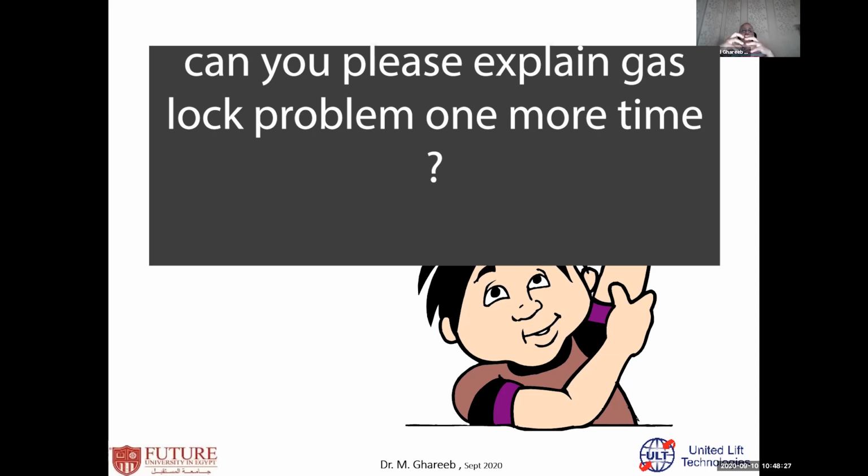If the volume of the cylinder is big, and the volume of gas is small, and the temperature is less, the pressure is low. Then the traveling valve will reach the lowest point, near the standing valve, and is not able to create a higher pressure than the hydrostatic head. That means the traveling valve will not open.